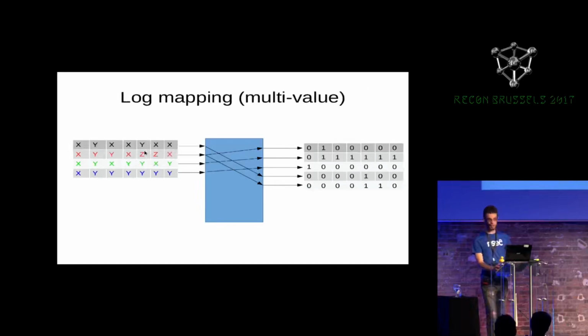And so also there are multi-values. So when you go into FPGAs, things are not just lookup tables where you have binary values. There are also some routing elements, muxes actually, to set which wire drives another wire. So you have to find a way to match these multi-values to an actual point and address set.